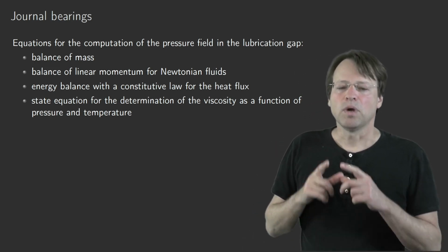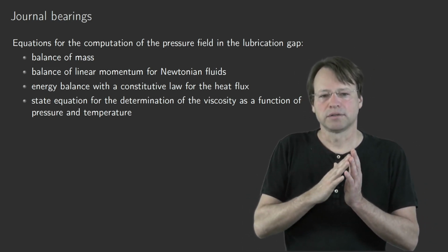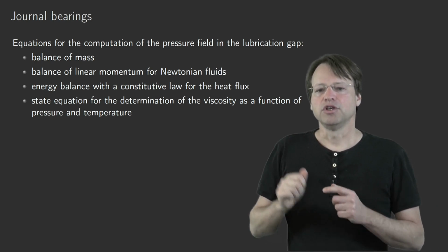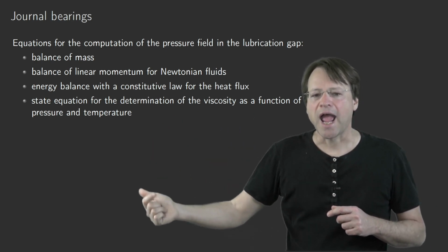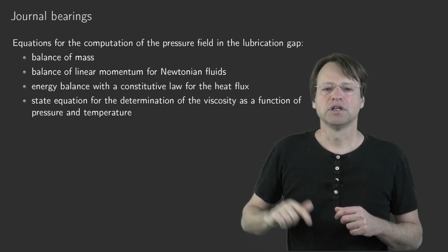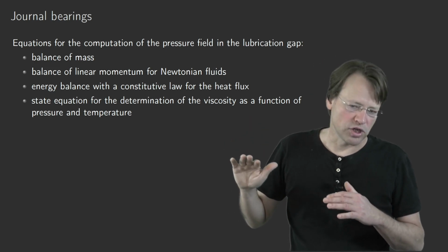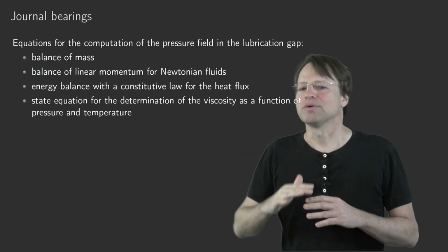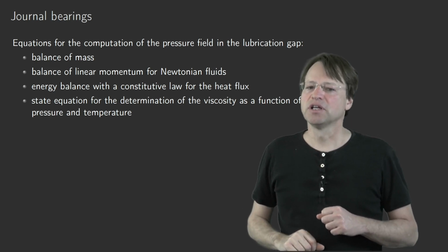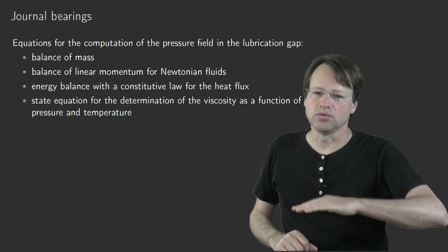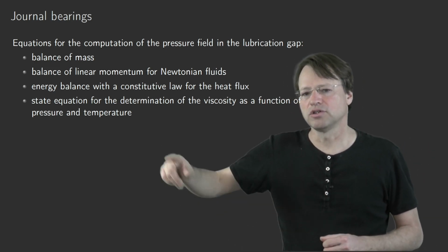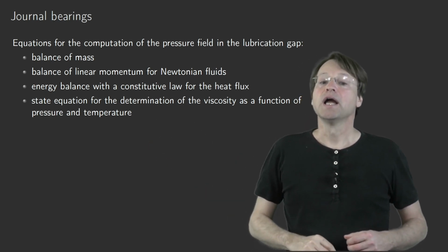No? What happens now in the convergent part of the lubrication gap? You increase the pressure and you increase the temperature. The viscosity would like to increase due to the increase in pressure and would like to be smaller due to the increase of the temperature.